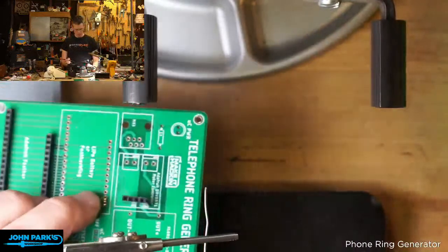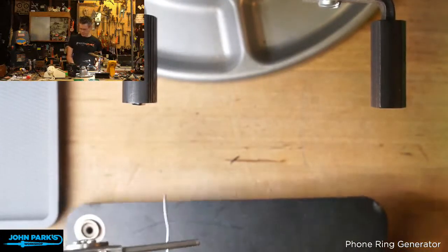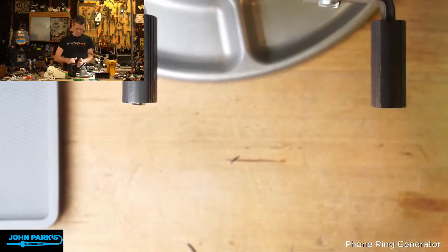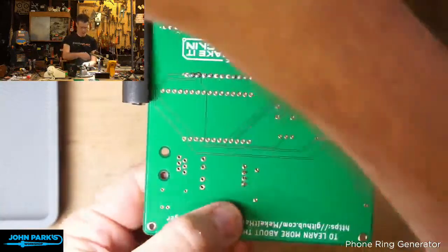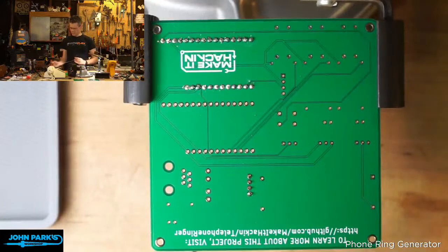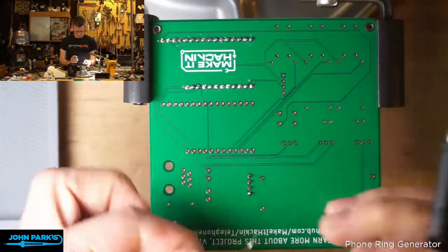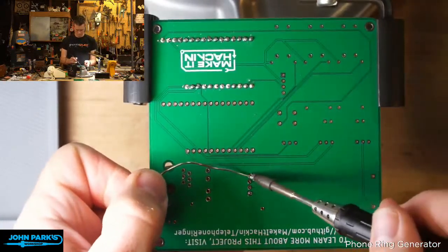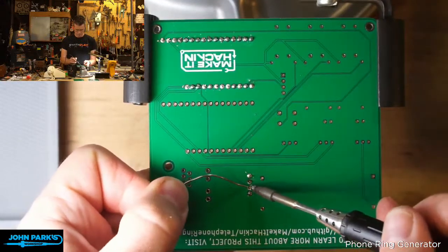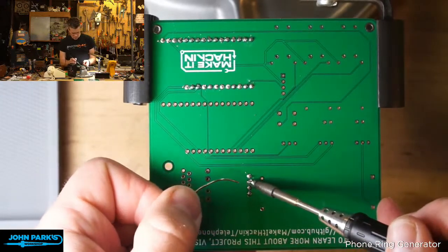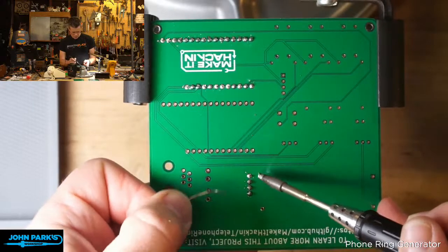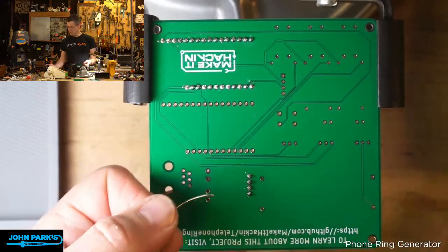And there you go. In this case, I can just get the first one started on there, and then I can get this out of the way. I'll just snap off some of that solder and leave it connected to the hobby hands holder there. So now I can place this back like so and solder the rest of that in place. By the way, if you're ever soldering stuff and you're wondering why one pin takes forever to heat up on your board, that's probably a ground plane. The ground plane will actually suck off a lot of heat.